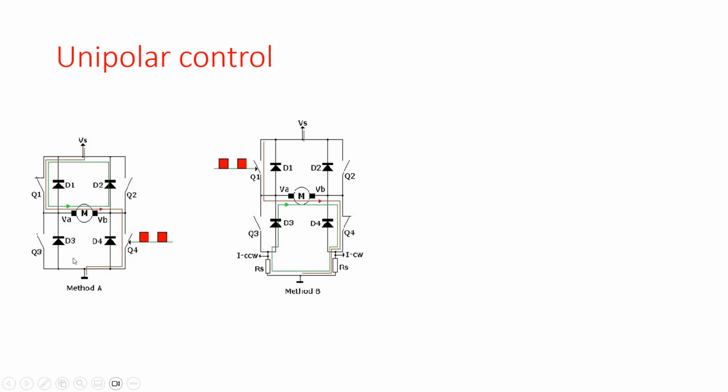And as you know, within these MOSFETs we have anti-parallel connected diodes, D1 through D4, and we are going to see that we need these diodes for operation of these different H-bridge types. So what I'm going to do now is look at the behavior of this H-bridge, and we are going to look at the voltages and the current flows.